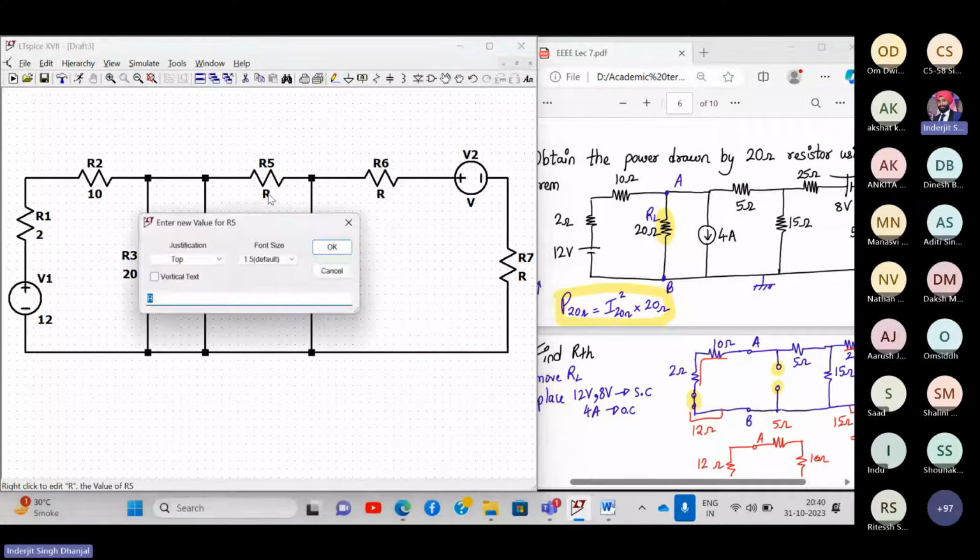All right. Now I'll add the voltage source. Maybe I'll cut this wire a little more. Now I'll add a voltage source over here of known value. You can give 1 volt or 10 volt, it's absolutely fine. And connect them together like this. Now this voltage source, I'm calling it Vx, let's say Vy. And I will give a known value to it, 10 volt. Now, if I simulate, the current flowing through this voltage source, if I divide the value of 10 volt by the current flowing through it, it will give me RTH. I will show it to you how.